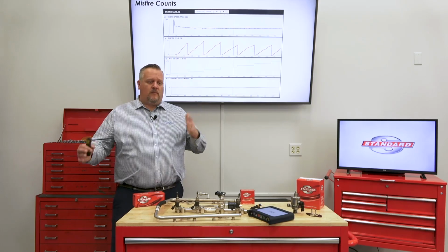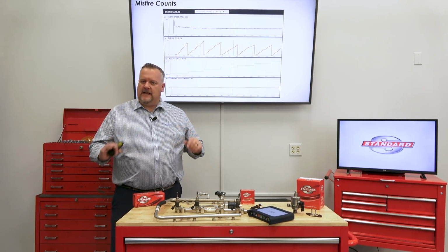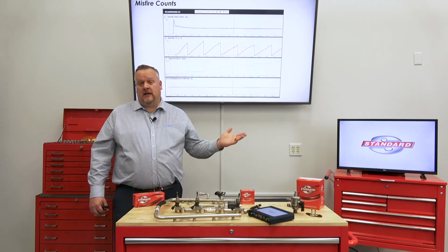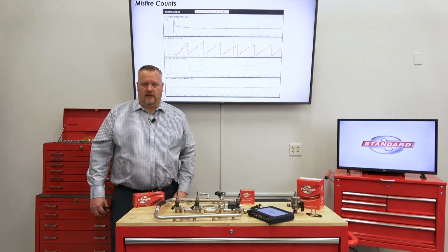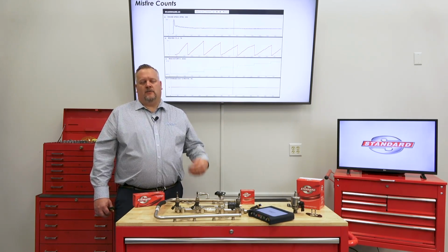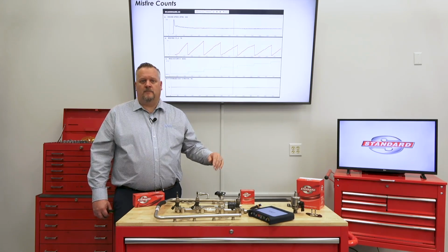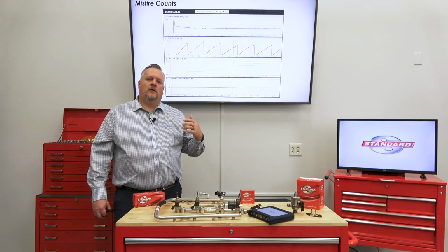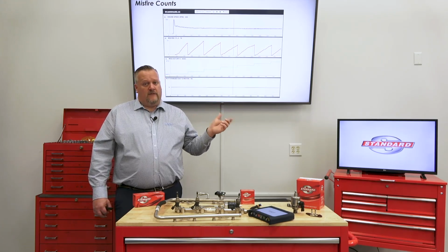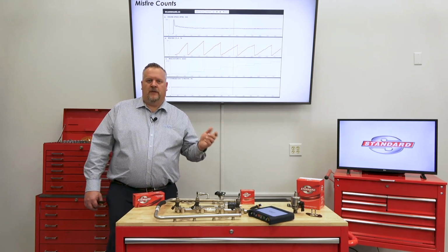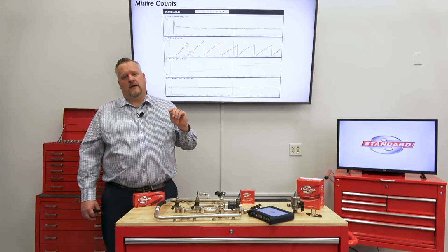Now, misfires off idle can be a lot of different things, but again, with experience, in my mind, I'm not thinking I've got an ignition-related problem yet. Predominantly, we're going to see our ignition-related problems occur under heavy load, where we're loading that ignition coil. So I'm thinking maybe we've got some sort of vacuum leak here or some sort of fuel starvation issue that's occurring with this vehicle at idle.